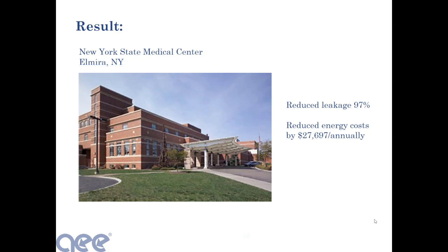Yes, ma'am. How are you calculating your leak rate? So the way we're doing it is kind of the industry standard practice. We do a static pressure test, which is we have a digital manometer. So what it's doing is it's reading the static pressure in the ductwork. It's ramping up the variable speed fan to maintain the pressure in the ductwork, and then it's using the other lead from the manometer to read the amount of flow that's going into the duct. So flow in equals flow out. Does that make sense?